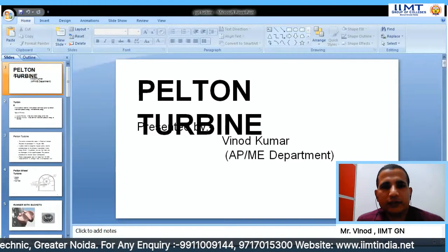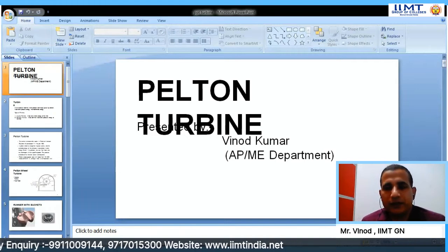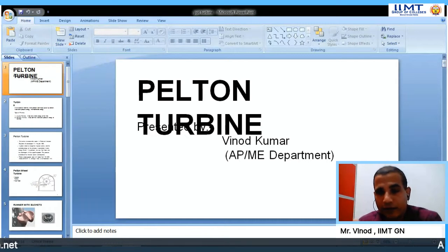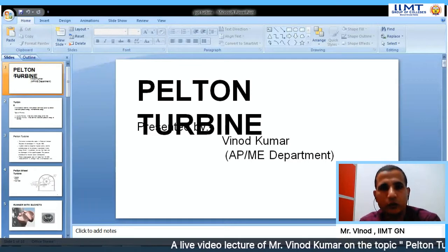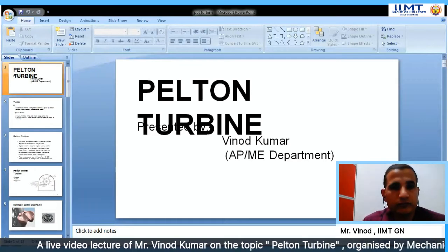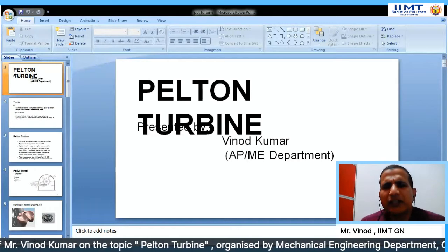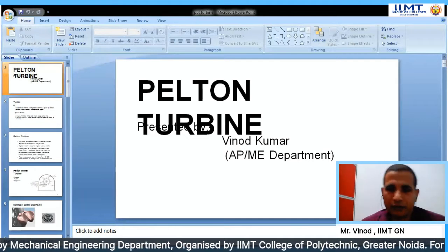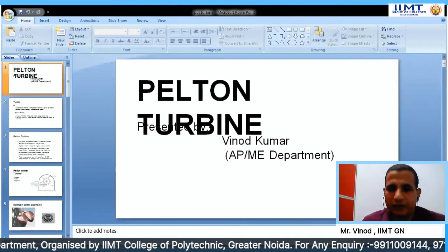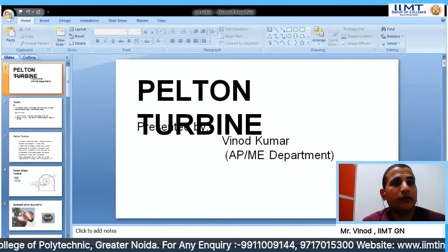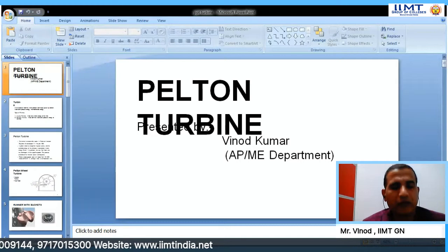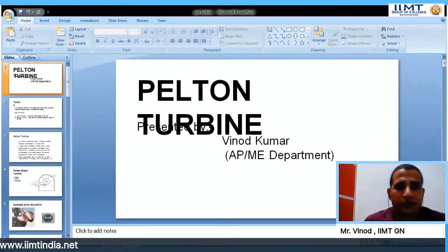Now you can see the mechanism of the splitter. This is the spear with nozzle, and the jet of water is split into two equal parts. Now come to the governing mechanism. Governing is nothing but the spear and nozzle element. As we push the spear forward, we decrease the discharge and hence the speed of the turbine. These are the applications. In the applications, we see that power can be generated with the help of the turbine. Thank you.